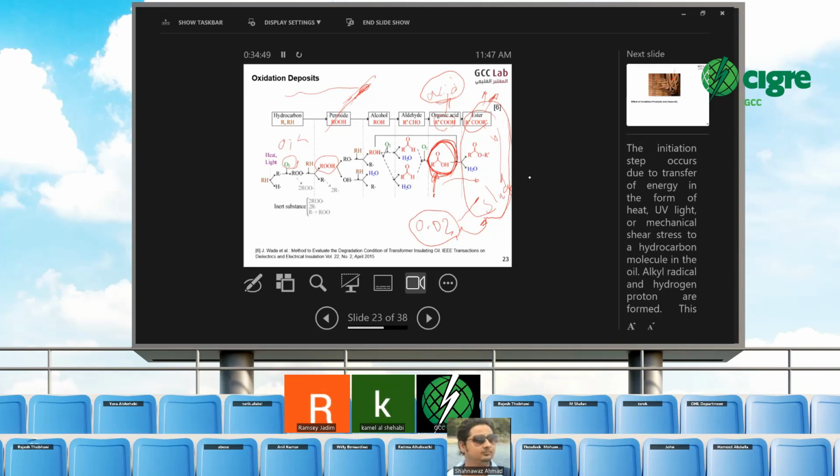Okay. Do you know where we found the problem? The earth line, there is something, a screw or something like this. It was open, loose, and this one gives a spark all the time. So it is something you cannot think about, but it happened. Some screw, something, maybe this connection in the cable box was not very tight, there's some looseness, something like that. Maybe. But as I told you, sometimes you open the unit and you don't find any problem, but still the problem remains. That means there is something.